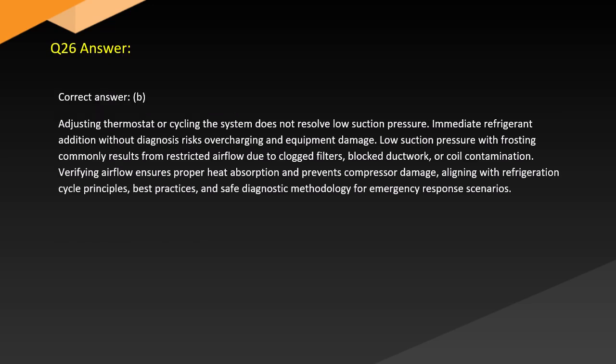Answer. Correct answer: B. Adjusting thermostat or cycling the system does not resolve low suction pressure. Immediate refrigerant addition without diagnosis risks overcharging and equipment damage. Low suction pressure with frosting commonly results from restricted airflow due to clogged filters, blocked ductwork, or coil contamination. Verifying airflow ensures proper heat absorption and prevents compressor damage, aligning with refrigeration cycle principles and safe diagnostic methodology for emergency response scenarios.